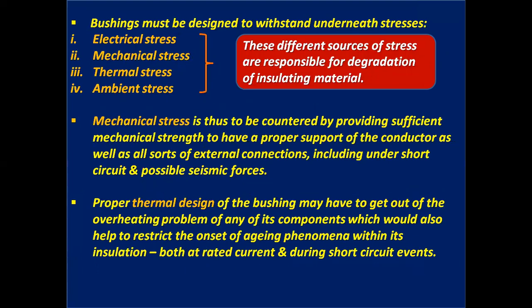Bushing must be designed to withstand the following stresses. Number 1, electrical stress. Number 2, mechanical stress. Number 3, thermal stress. And number 4, ambient stress. These different sources of stress are responsible for degradation of insulating material.